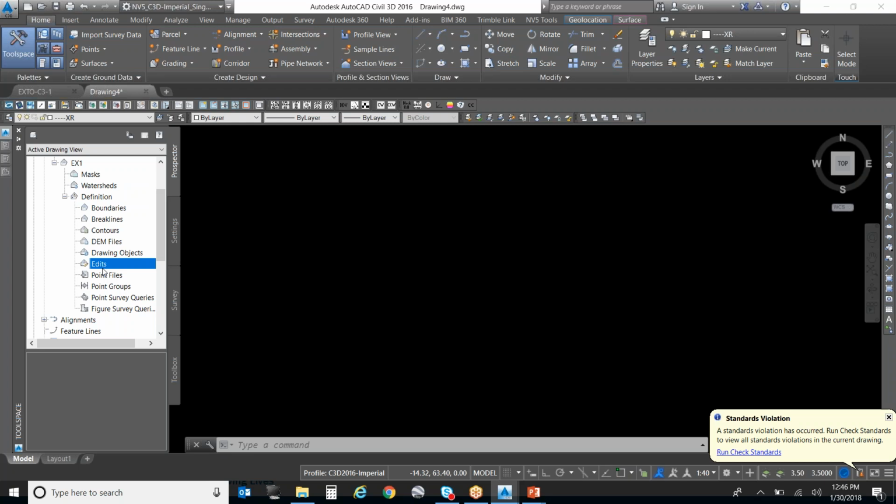You're going to get to that? Or no? No, that's a very good point. And actually, you'll notice that there's not one in the template. I will probably add one to the template. That was kind of an oversight on my end, quite frankly, to pre-exclude some inverts. The one thing you have to be careful about is flow lines, because sometimes a flow line is the flow line of a gutter, which you'd want to include, but sometimes they also do flow lines for dips. So some of the point group excludes.